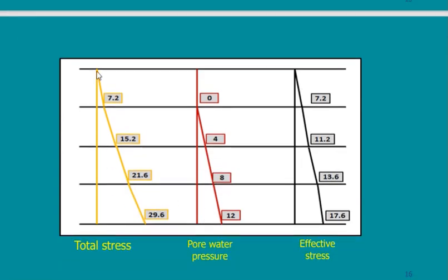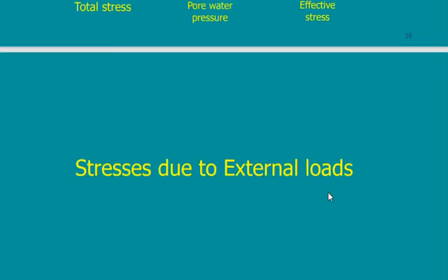This is the drawing. This is the total stress taken from the table, and this is the water. The difference between the total stress and the water is that the zero starts from the first layer. It is because in this example, but if I bring you another example with the water table at the top, then it will start from the top. Suppose I give you no water table, and I tell you to get the effective stress. The effective stress will be the total, because you don't have water. It is easy. Then I just subtract both from each other to end up with the effective stress.